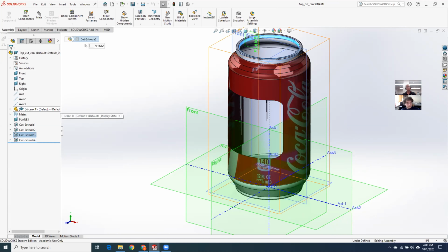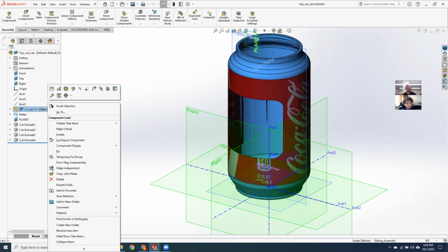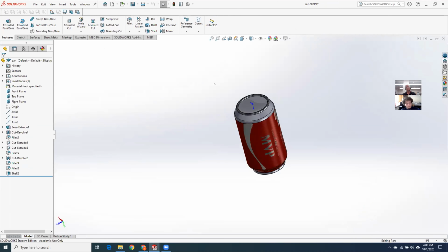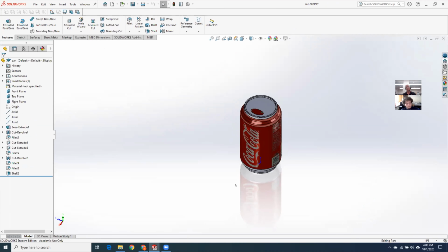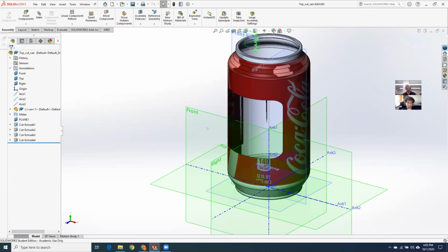So yeah, that's all I'm asking you guys to do. So when I open the can, it is whole. And this is just like any of those cast pieces that I used to put in a jet engine. And then when we bring it up to the next assembly level, we would take that cast part and we would grind the hooks, grind the faces, grind the important mating surfaces. And doing all of these cutting operations is exactly analogous to what we did to finish castings that go in a jet engine.